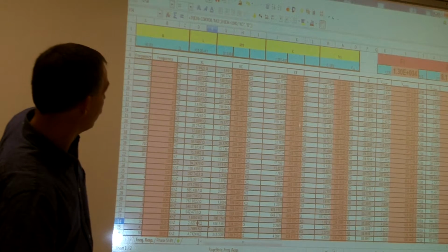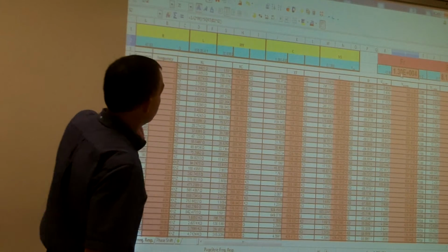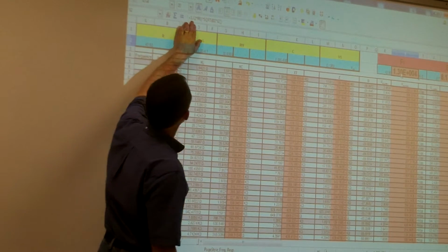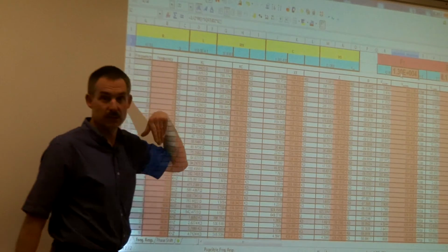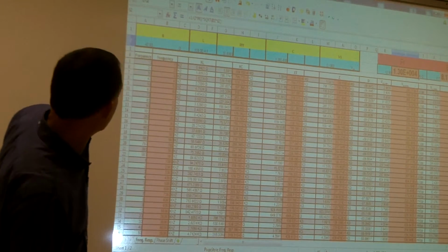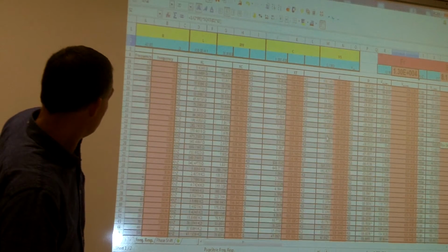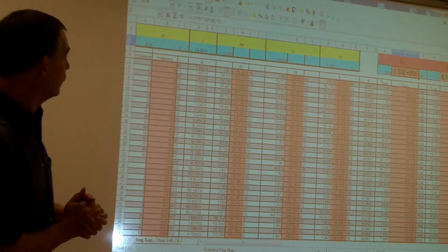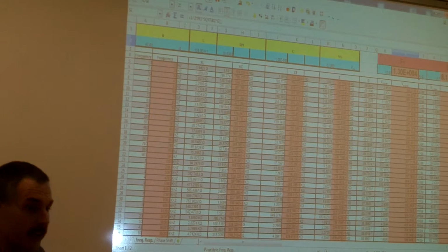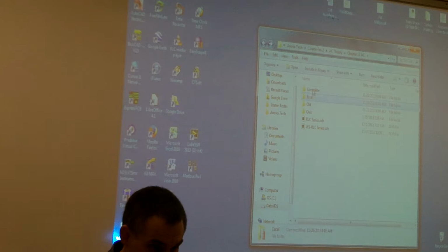So we did a lot of that stuff, and we really learned how to use Excel. Here's all our formulas, like for calculating our resonating frequency. Here's 1 over 2 pi times the square root of our inductor and our capacitor. So we did a lot of the formulas at the same time. And this one wasn't quite so bad. But the other one, we also did the frequency response curve of just our RLC circuit. It's amazing what Excel can do for you and how you can graph it.